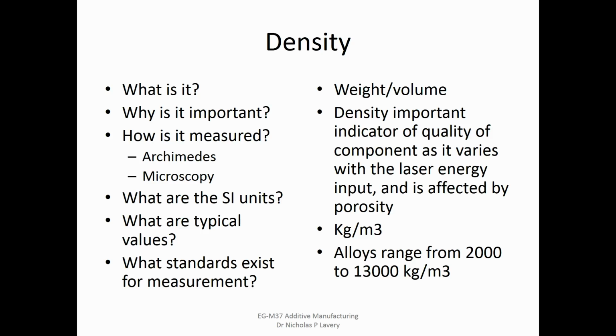The smaller the parts, the lighter or the less dense the parts, so if you're trying to do aluminium, those errors in the measurement become very important. As the porosity goes down, it gets even more difficult to measure the density. If you're trying to work out the difference experimentally between something that's got 0.5% porosity and 0.7% porosity, it's very, very difficult.